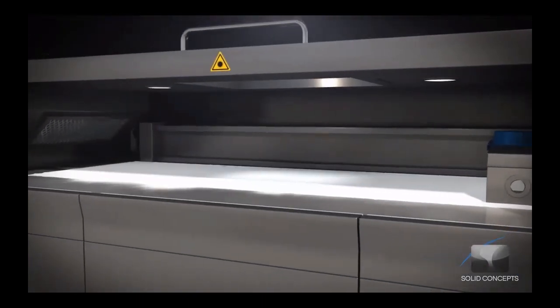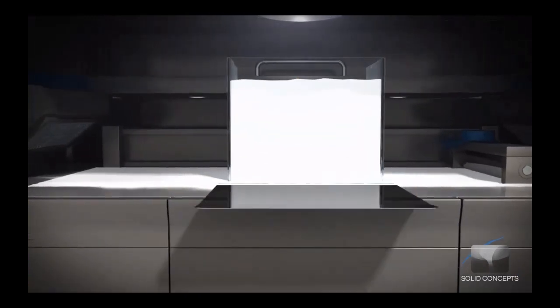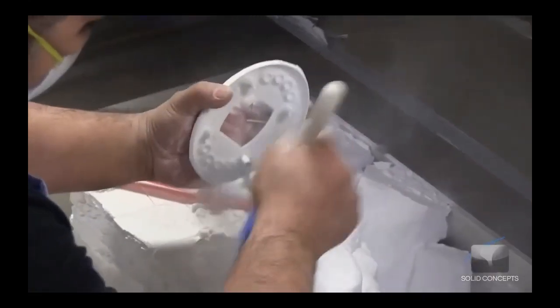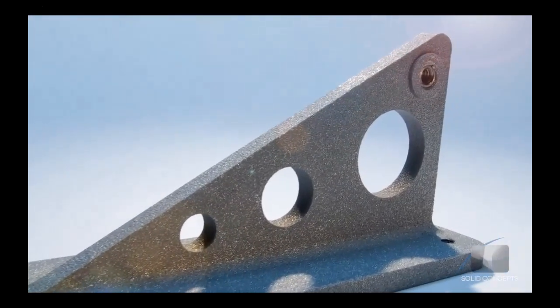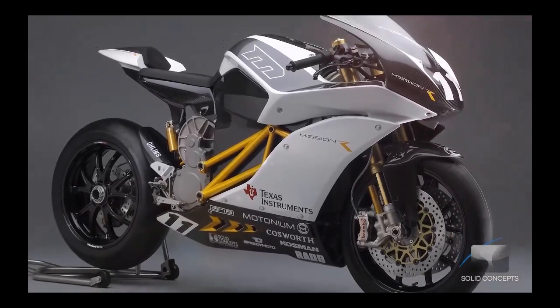As SLS parts are built, they are encompassed by unsintered powder, which provides supplemental strength and eliminates the need for support structures. Complex designs and assemblies, once thought impossible, are now being redesigned with SLS as cost-effective integrated structures. Solid Concepts manufactures parts utilizing nylon with property-enhancing fillers to create rugged SLS parts suitable for a variety of prototype and production applications. Typical uses for SLS include tools and fixtures, fuel tanks, flight-rated components for unmanned aerial vehicles, automotive designs, air ducts, architectural models, and artistic sculptures.